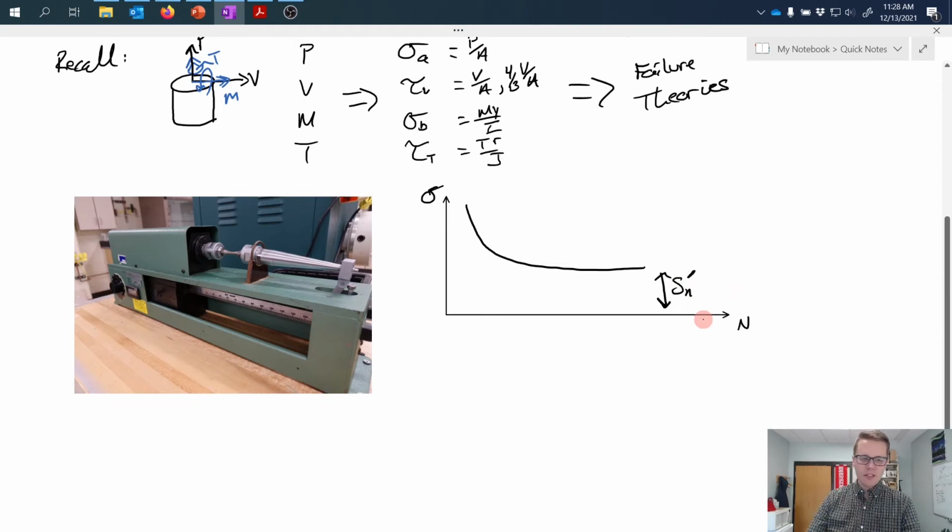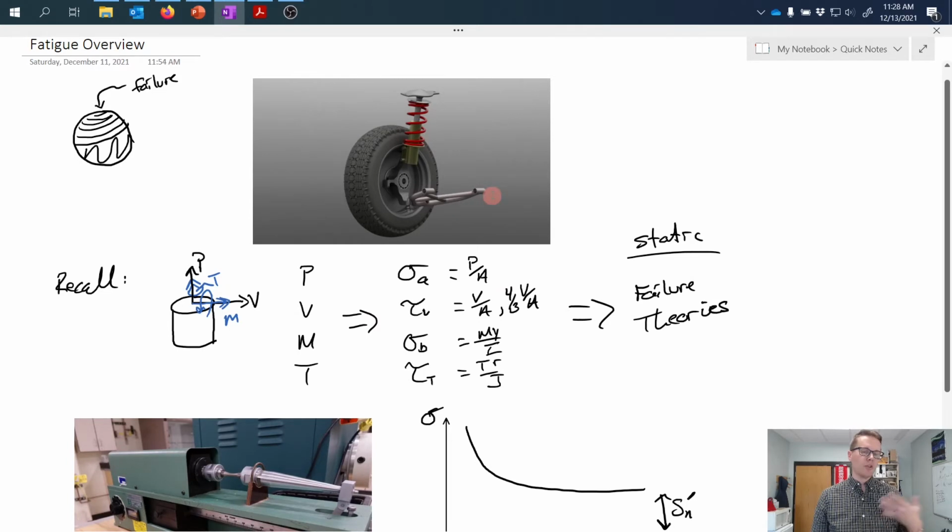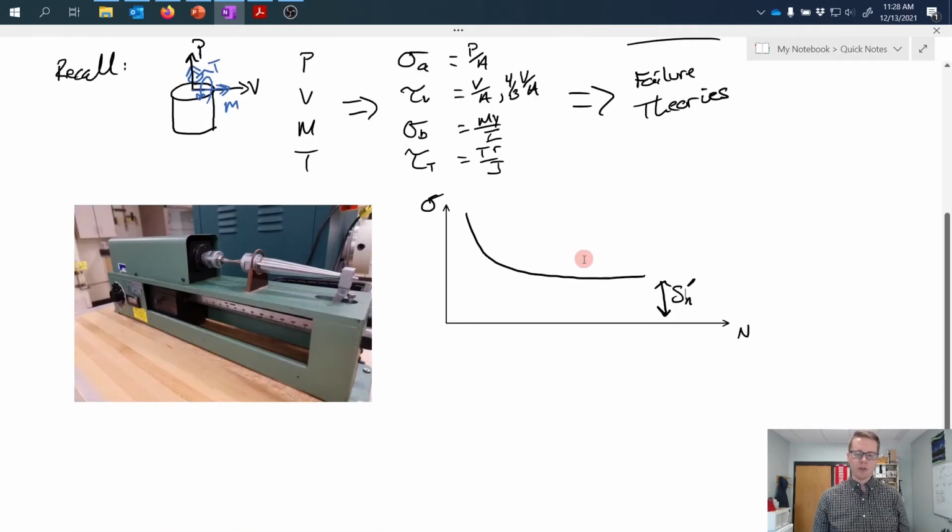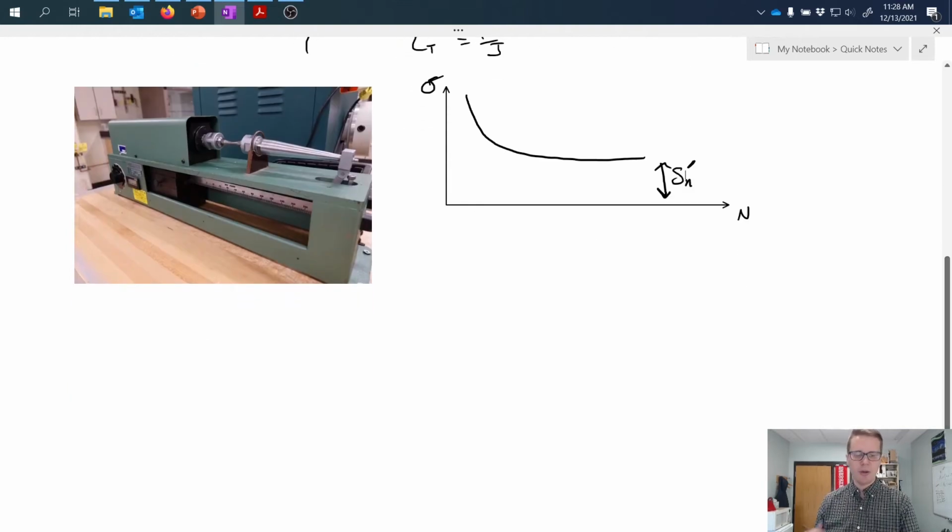Now, tests performed on a fatigue tester like this are operating under relatively ideal conditions. We try to have high quality test specimens. We try to very tightly control the conditions under which we're doing that. And of course, that isn't reality, right? There isn't some idealized scenario when we apply a load to a car driving down the road. There's all sorts of different confounding factors. So to take that into account, we make predictions about how those confounding factors may reduce the overall stress limit that we have for our part.